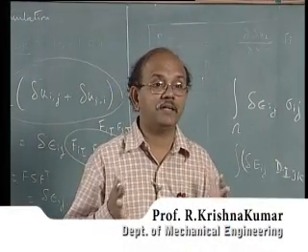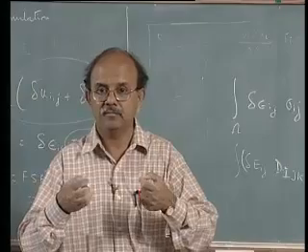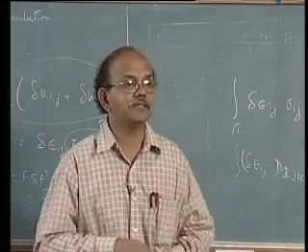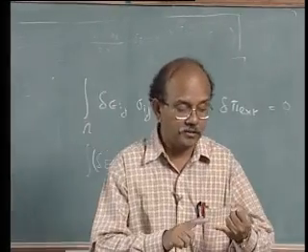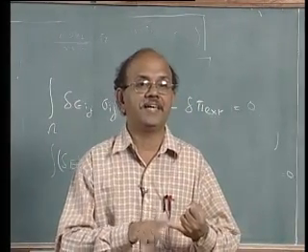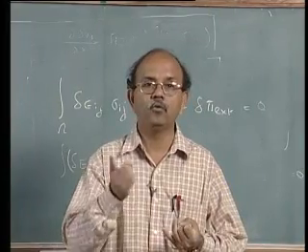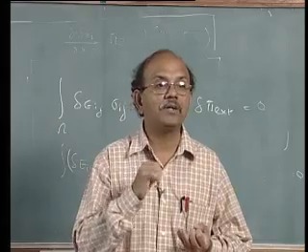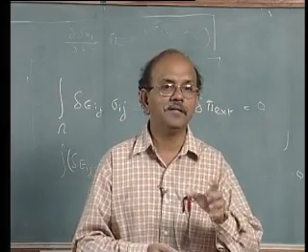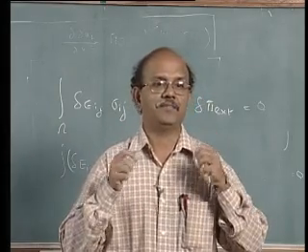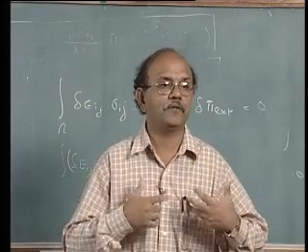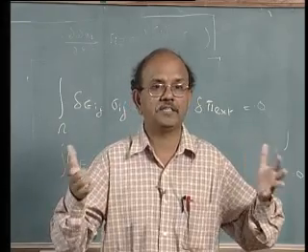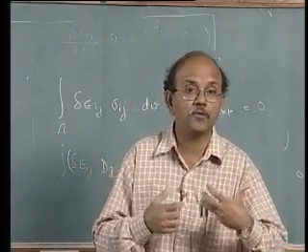So I have to calculate an equivalent d in the current configuration. In other words, note this carefully: we know how to transform stress. We know how to transform strains. Just saw it. How do you now transform the D, that is capital D, which I can call the tangent elastic modulus?